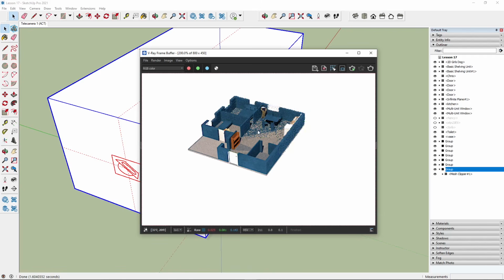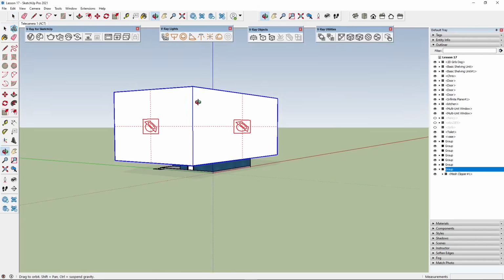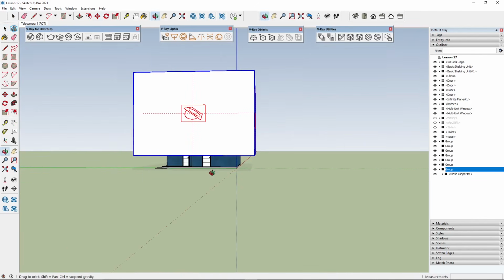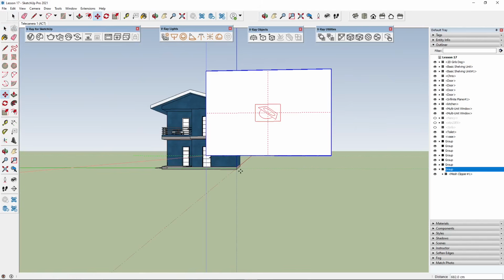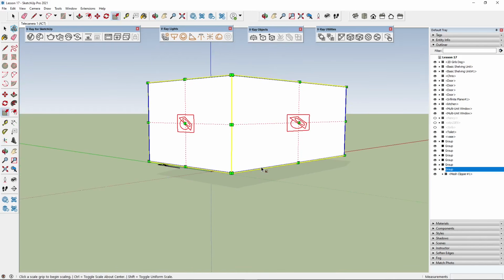Okay, now be careful not to have two surfaces in the same position, otherwise you're gonna get strange effects. You need to delete one surface or the other, otherwise it's gonna juxtapose and create that effect. Now if I want to create a section, I just need to move this in another position, so like that, and let's stretch this again with a scale.